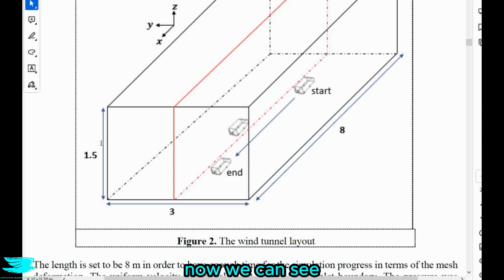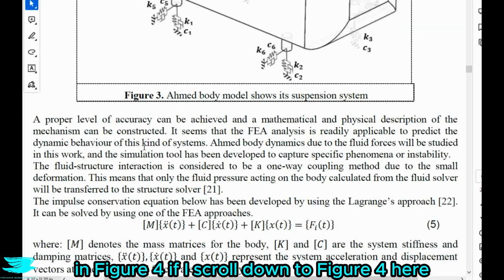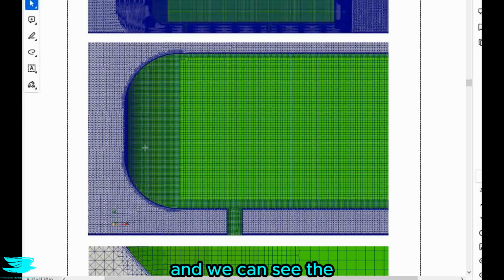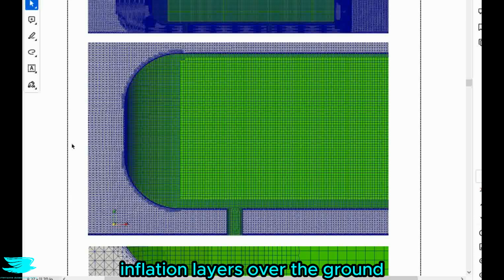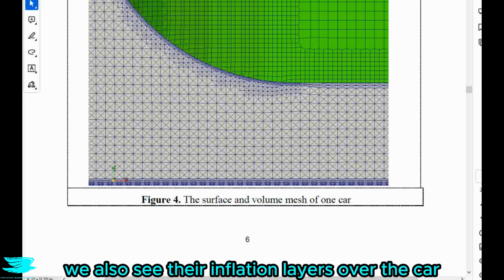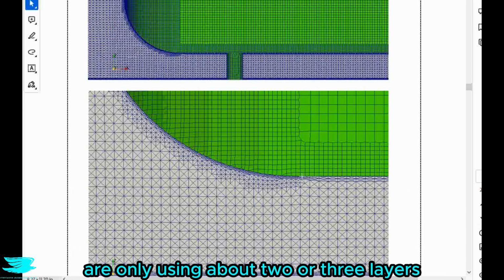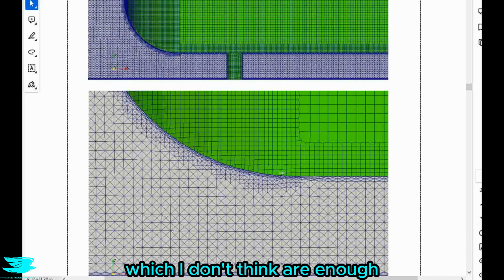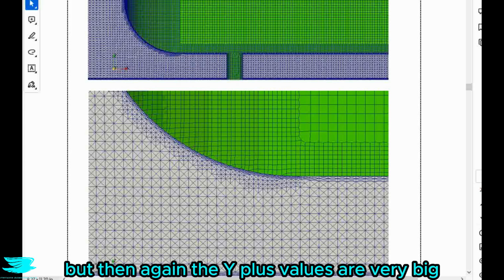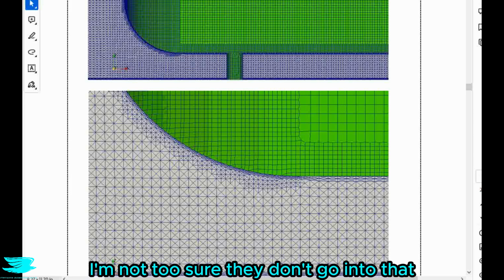Now we can see their surface and volume meshes around the cars in figure 4, if I scroll down to figure 4 here, and we can see the inflation layers over the ground in the bottom figure here. So zooming in here. We can also see their inflation layers over the car, but it seems like they are only using about 2 or 3 layers, which I don't think are enough. But then again, the Y plus values are very big, so maybe the boundary layer is about this size too. I'm not too sure, they didn't go into that.